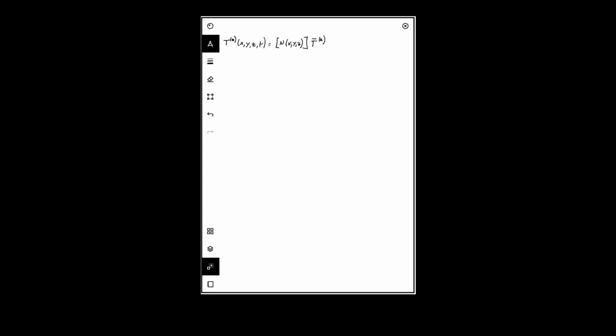Then we have step 3. In the Galerkin method, the integral of the weighted residue over the domain of the element is set equal to 0 by taking the weights same as interpolation function Ni. Step 4. After including boundary conditions and performing calculation, we can assemble the overall equations.